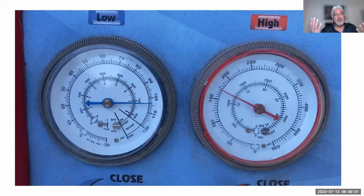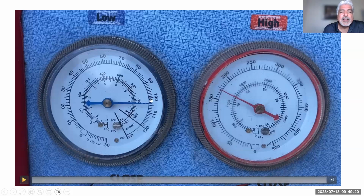So when you check initially, you hook up your gauges and you haven't done anything, let's say we're on the assumption that the system is charged, you should see the same pressure on the high and the low side. I had run this before, so I need to re-record this later. What's going to happen is, does that pressure match the temperature pressure relationship chart, which we'll cover later?